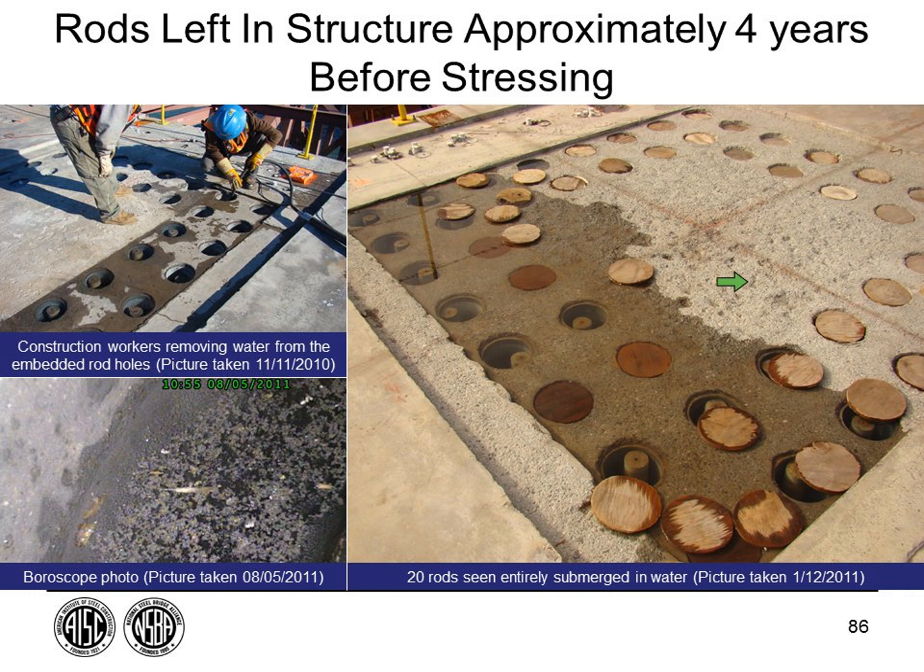What happened was they're sitting on a horizontal surface out in the bay, and it rains and the water gets in there. They weren't sealed. What they're doing here is trying to remove some of the water, but there was water trapped in these, and when they grouted it, they weren't able to eliminate that water.